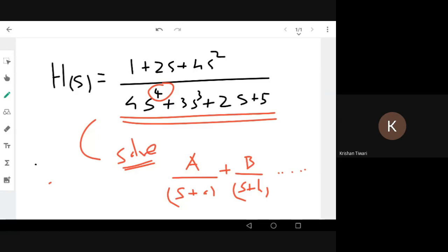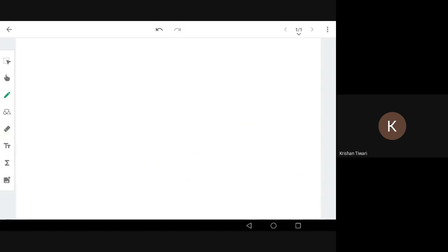So then we go for the Routh-Hurwitz criterion, right? Later we'll see why we are using it. Basically, we are analyzing whether the poles are remaining on the right side or left side, or how many poles are on the left side or how many poles are on the right side. So we are determining whether the system is stable or not by predicting how many poles are on the right side. That is what the Routh criterion is telling us. Okay, let's jump to the Routh criterion.